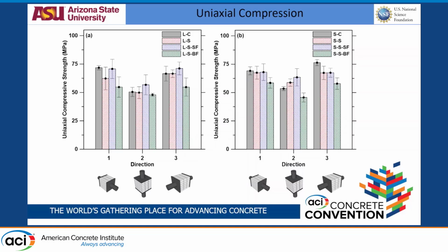We have papers where we do just single filament prints, where we have the cubes. Here we have 3 filaments side by side in the cube, so we do see that interfilament effect. If we print a 60 mm wide bead and use just 1 filament, we will not see the interfilament effects. So interfilament effects are significant in these systems. We have to reduce the interfilament defects and the detrimental effect of those interfilaments. So what can we do to further increase it?